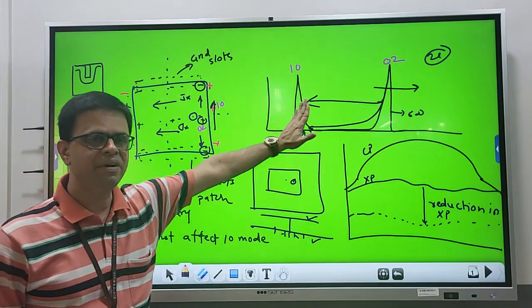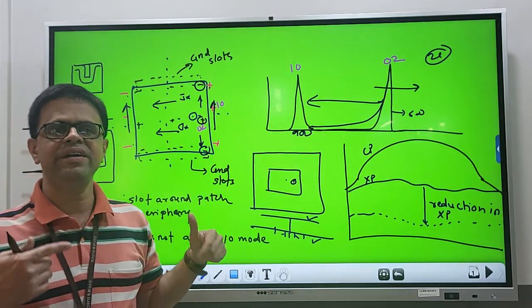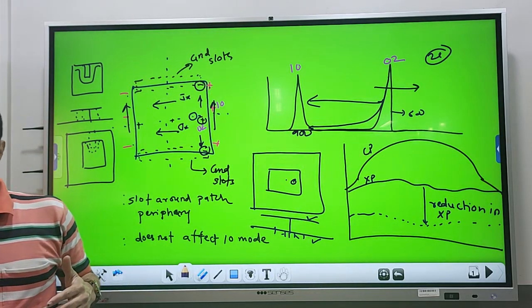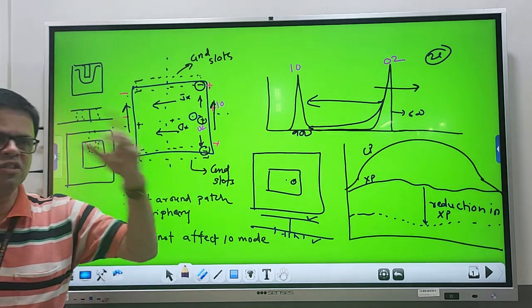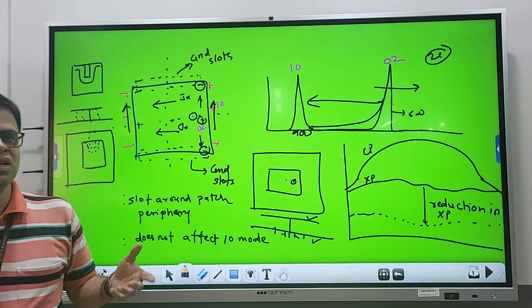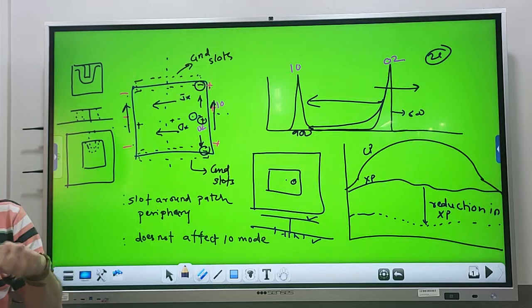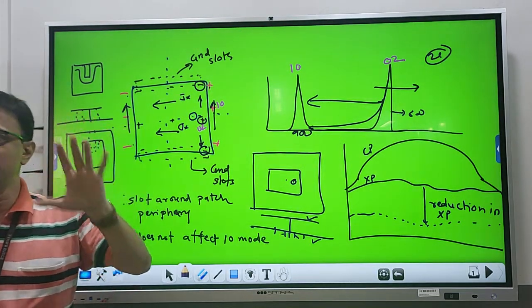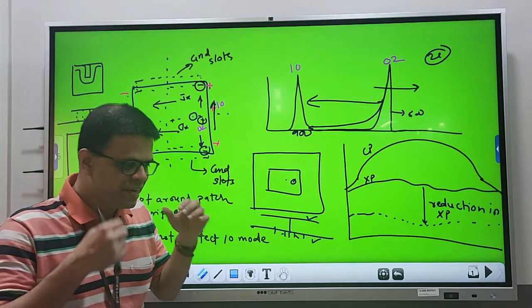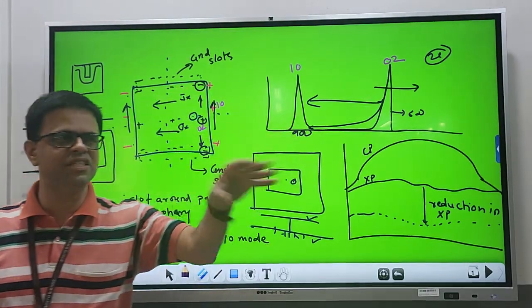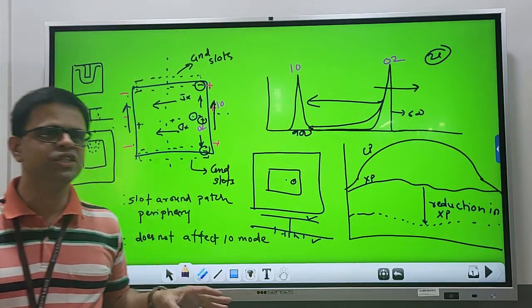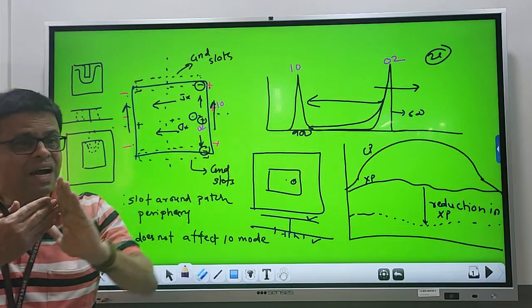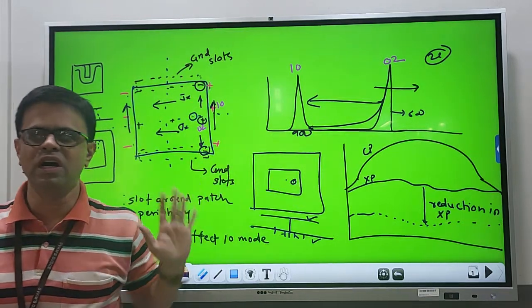Okay, so this is the fundamental, because from here all research related to the defected ground plane structures evolved. Later on, the advantages of defected ground plane structures with respect to compact size, wideband, multiband response, or even circular polarization were investigated. But the basis started from here. So cross polar reduction is the most important aspect. And remember, for very sensitive receivers, cross polar should be minus 60, minus 70 dB down. And those kinds of reductions are only possible if I play with the positioning of all higher order modes, if I isolate my fundamental mode with respect to all higher order modes.